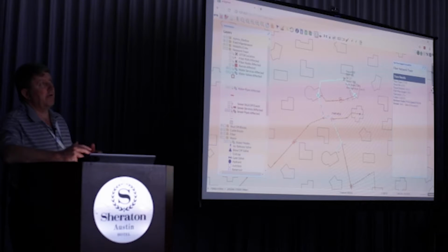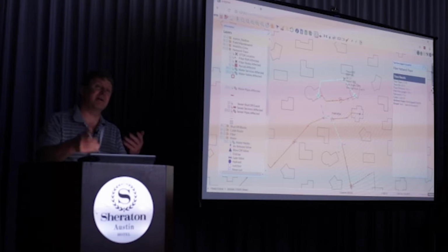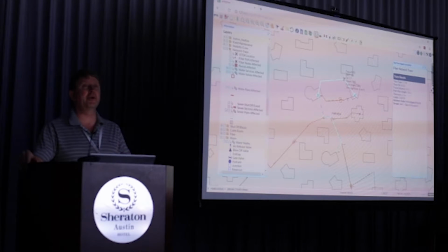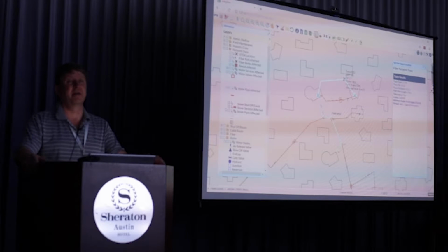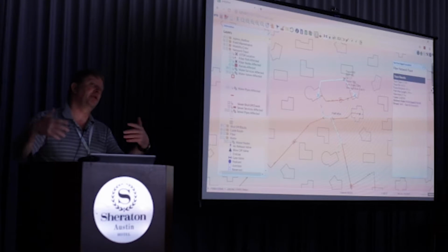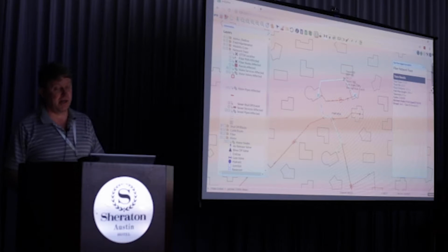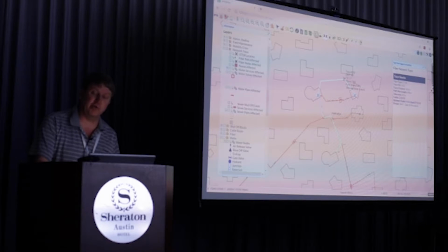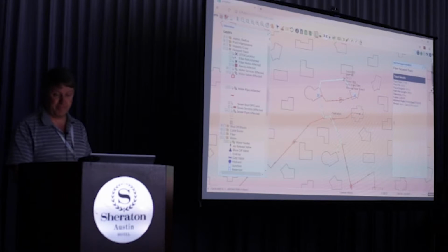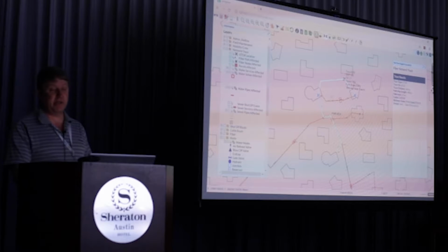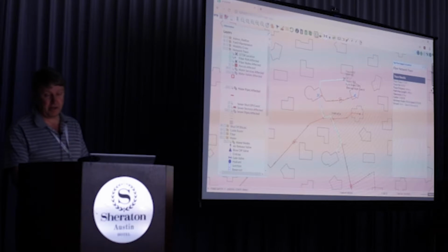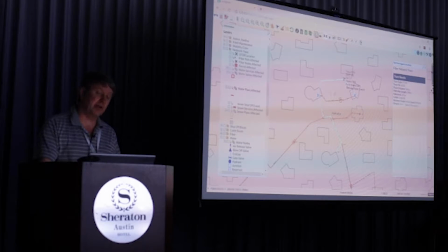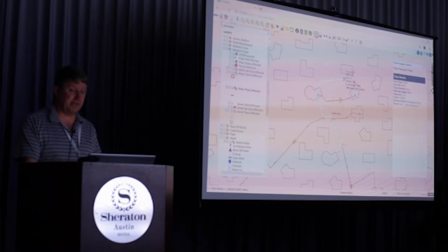So very often you don't know, they've got loops in the cable, but you don't know on which side it is, so it will go and calculate a tolerance for you on the last cable segment, of the difference between your geometry length and the actual cable length, and give you where you can go and look for that particular problem. And it will tell you it's in between these particular nodes, and on which tube you have the problem. So quite a big time saver there.